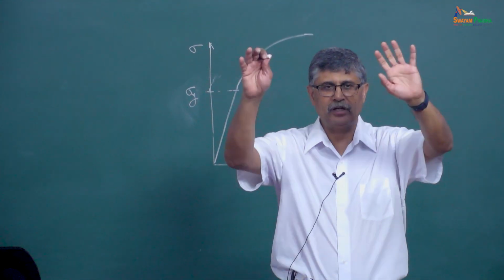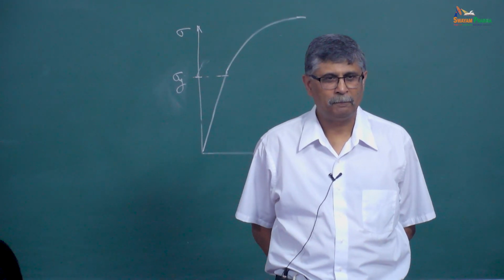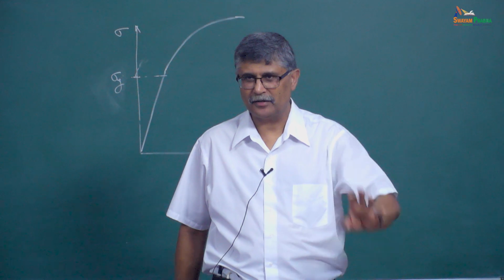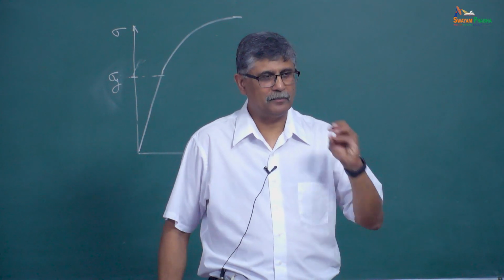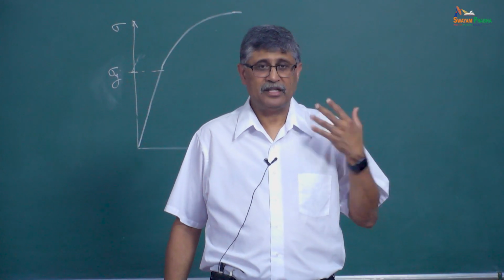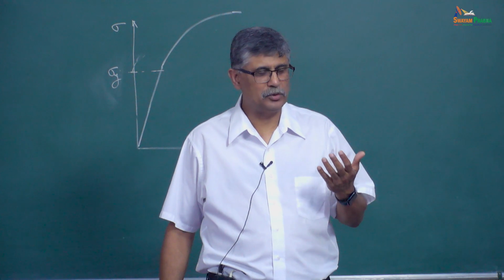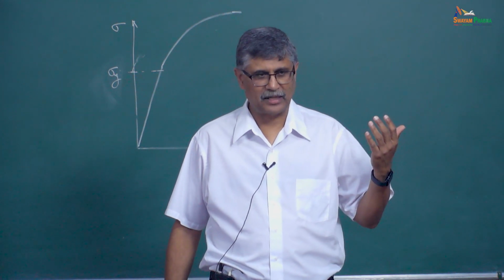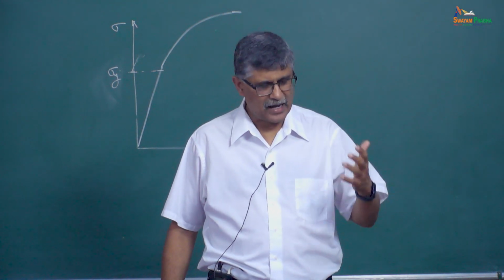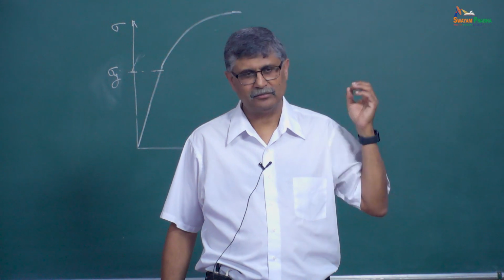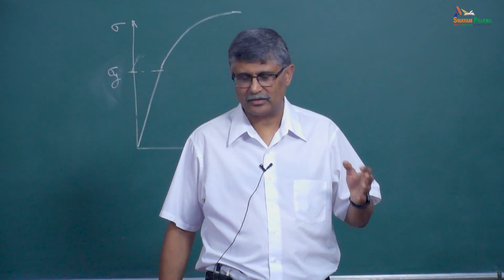How many of you here understand what dislocations are? Undergraduates? Okay, all right, good. So you know that in a material, you need defects to actually cause this deformation, plastic deformation. Defects such as dislocations, edge dislocations, screw dislocations, etc.